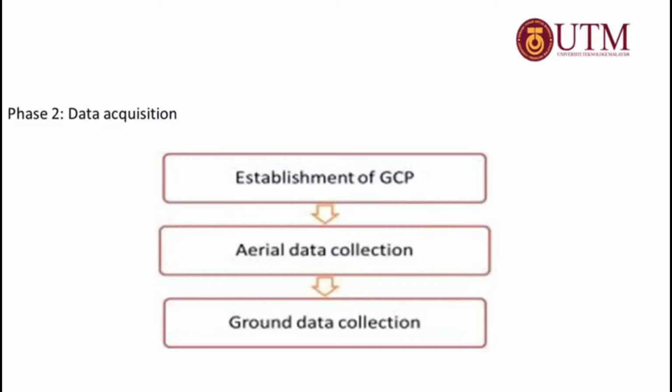The flying height was set up to 50 meters above the ground and overlapping was set up to 70% side lap and 60% of end lap. A higher altitude will result in objects far in distance, meanwhile shorter altitude to the ground is not suitable. The total number of flight stripes is 7 stripes and the flight took about 5 minutes. The study area for data acquisition involved was the rooftop of T06 building.